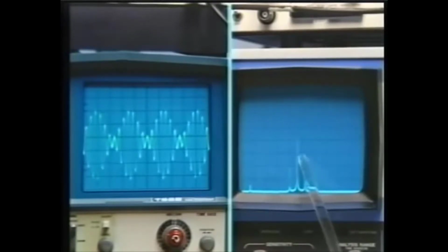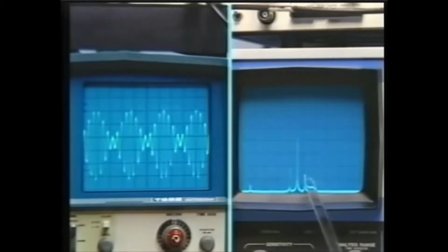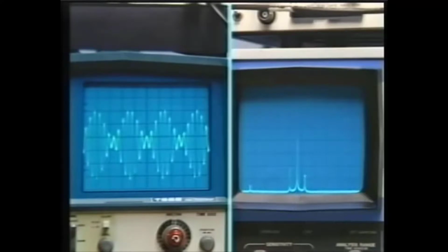And then on the spectrum analyzer, we have the spectral display, and this is the carrier signal, that's the carrier frequency, and these sidebands then correspond to the sidebands associated with the modulating signal. So this is the spectrum of the total modulated output, right? Right. It's interesting to vary some of these parameters.